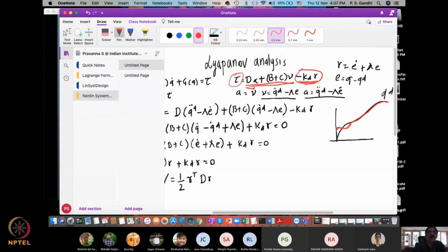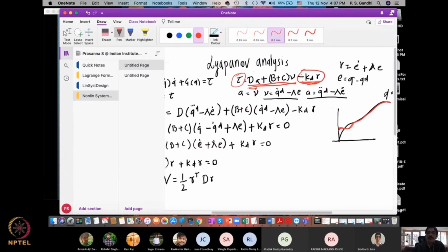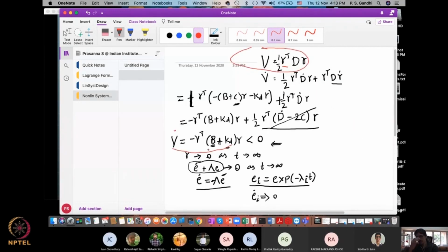Of course, all those things will come as an additional computation cost. So you see this controller computing will be much costlier than just having the feedback term computed, in terms of your microcontroller implementation. So that's how we should think about implementation and theoretical development together in some sense. Or you do the theoretical development and see, okay, is it really viable for my implementation or not? Those kinds of things need to be thought about. So that's how we start making conclusions.